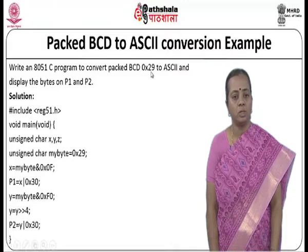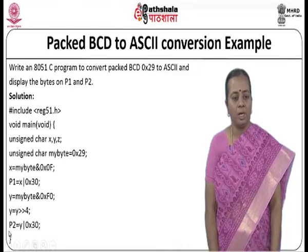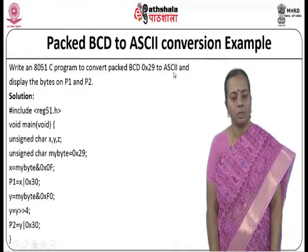Now, we need to convert this 2 also. So, mybyte is ANDed with 0F0, then this F is ANDed with 2 and 0 is ANDed with 9. So, 9 becomes 0, only 2 comes over here because it is ANDed with F. Now, because it is in the first position, I will be pushing it to the right side. Because of that, I will make y equal to mybyte right shifted by 4 positions, so that this 2 comes to 0 0 0 0 0 0 1 0. So, that way it comes.